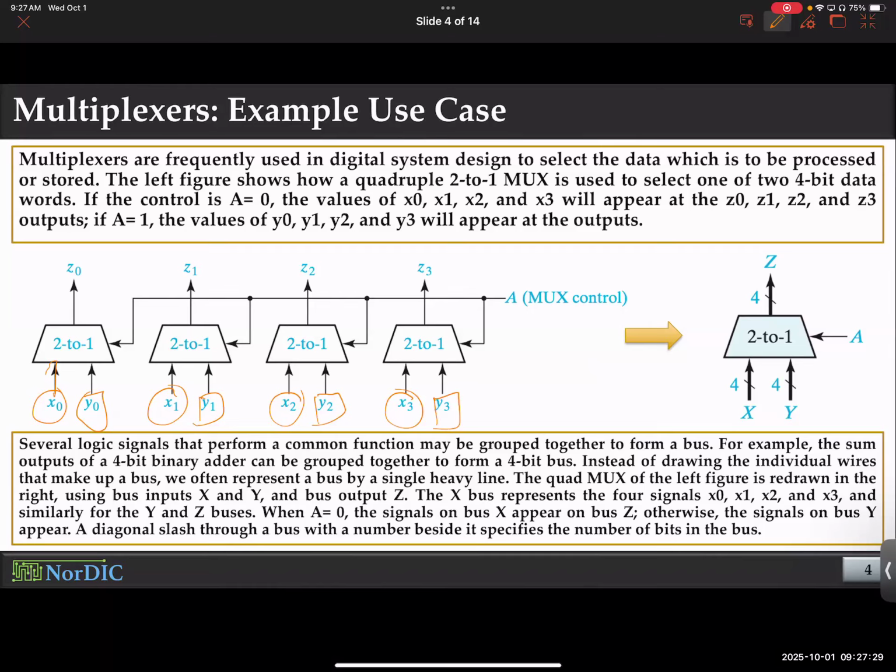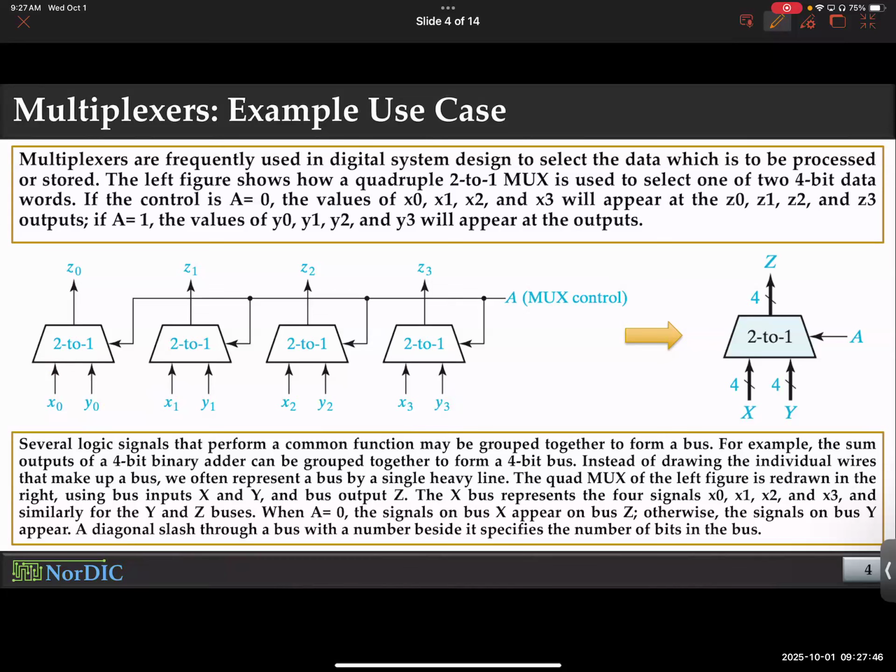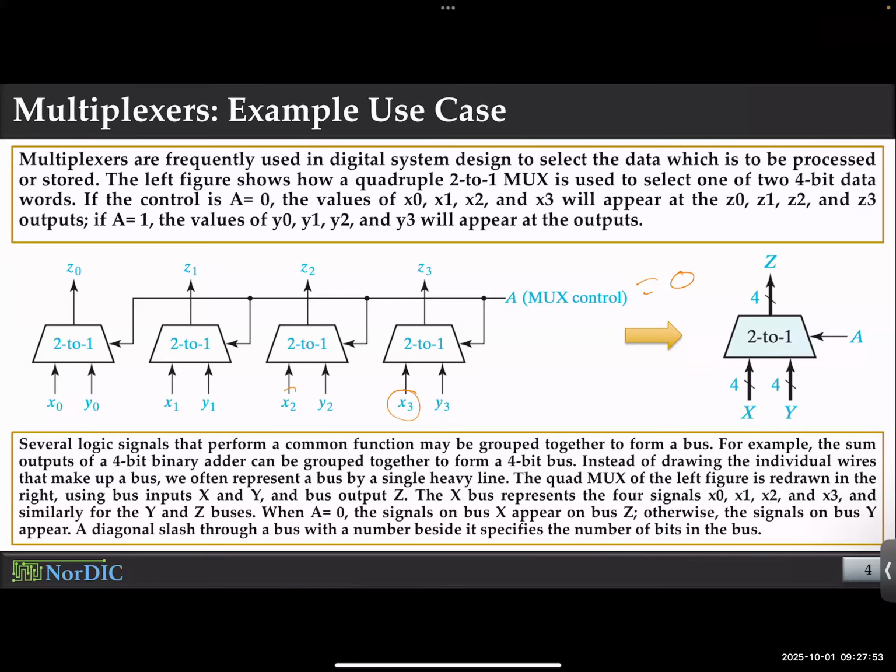So this is your select signal. This is a 2-input mux. That means you just need 1 bit of select signal. If you make it 0, it will always select X. If your select is 1, it will always select Y. So you can selectively load the number you want to use. You just control the select signal to say 0, and you have all the X components. Or you could convert it to 1 and you get all the Y components.